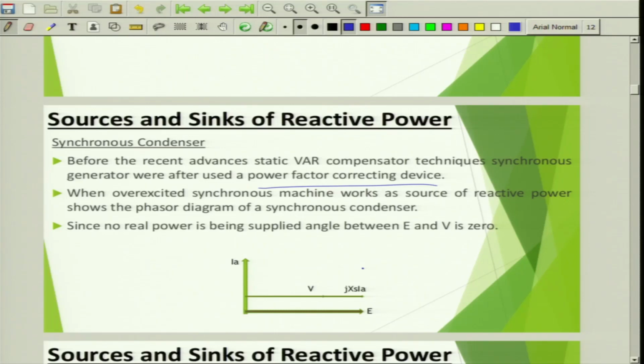If they are dependent upon the generating sources, and let us say there is a far distance, you have to pull the reactive power over a very long distance, which increases the losses, and you are occupying the whole transmission corridor. So there will be a high penalty imposed on these customers. So what they do is, I need reactive power, let me manage my own reactive power with my own equipment. So this synchronous condenser is a very important equipment.